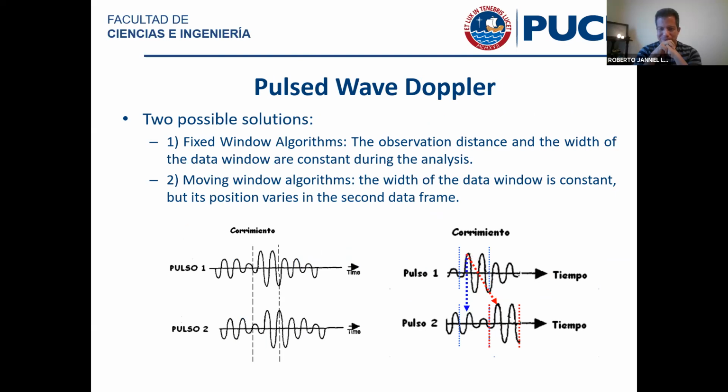What's the width that I'm using for the phase shift algorithm? It's just one sample. The only thing that I do is look at one sample in fast time, and I look at the sample at the same fast time in the next transmission, and I compare the phase that the signal has at those 2 points. That's the only thing that I do.